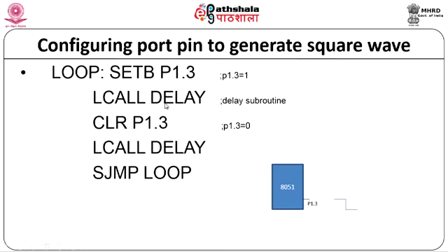This is a delay routine. LCALL is telling you that it is a subroutine long call, meaning this delay subroutine is written somewhere far away. So I will do a long call, go to that particular subroutine, run it, and come back. There I am not processing anything; instead I make some delay statements, putting in a loop. So I am not doing any work.